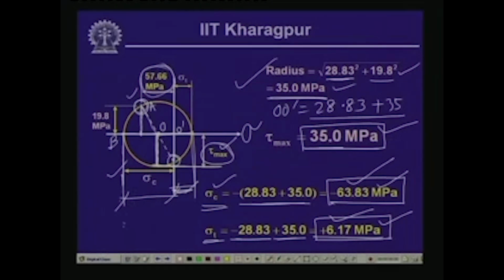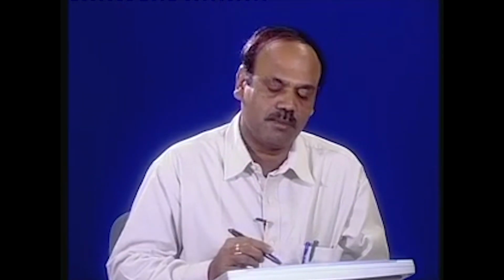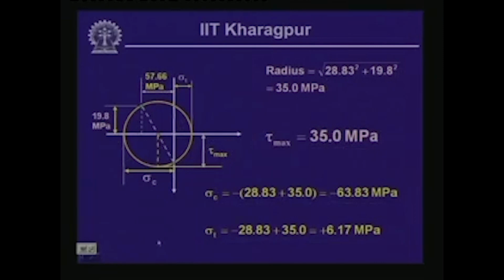So, these are the values at that particular point when the bracket is subjected to tip loads, one in the vertical direction and another in the horizontal direction, which is parallel to AB. These two forces compute the stresses at the support, which give the maximum tensile, maximum compressive, and shearing stresses of the magnitudes we have calculated here.